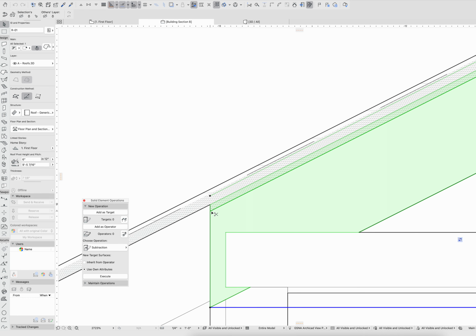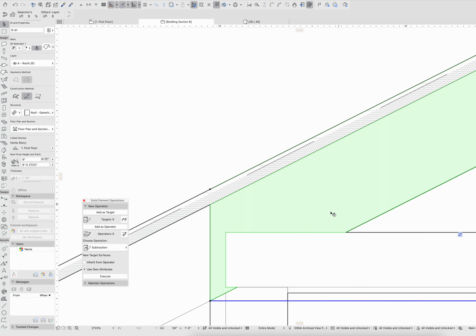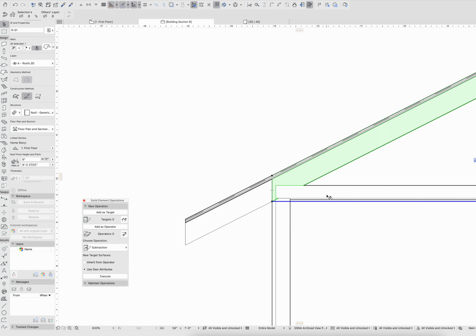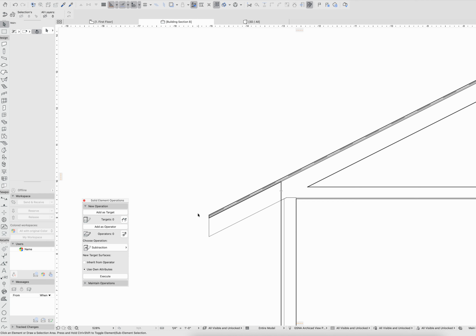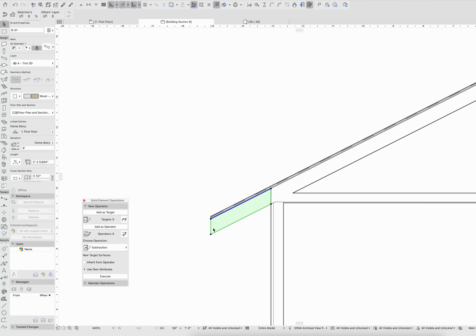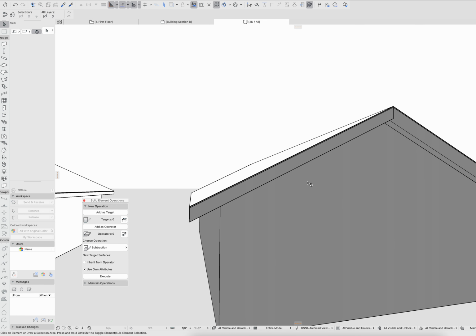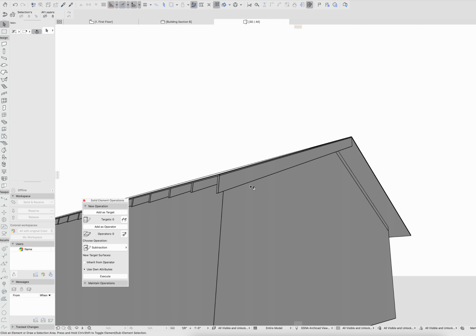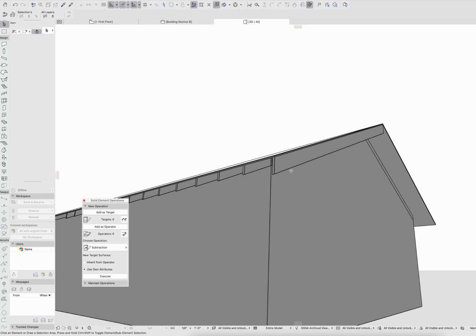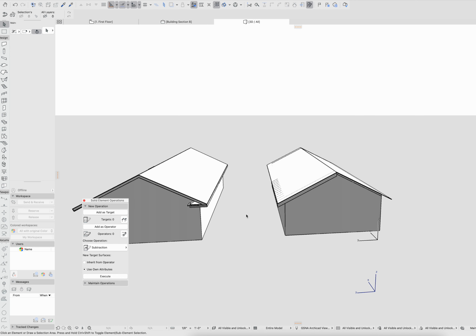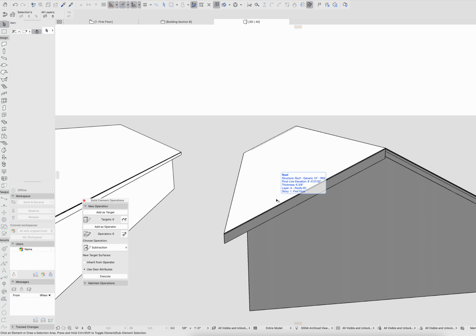Anyway, so you could also just get rid of the sheathing and the finish and just have this as a separate roof. But this gives you an idea of how you can get to sort of a higher level of detail. You can put your fascia, you can put your gutter, whatever on the outside of this. But modeling that with separate pieces like that gives you a higher level of detail. You could put corbel brackets or outlookers, just sort of piecing it together with separate beams and adding more detail is going to be the way that you clean up your sections, clean up your elevations, make everything live to the model in all of your documented views.